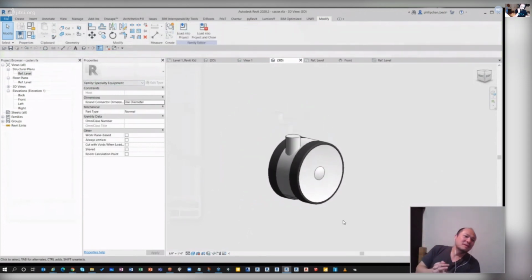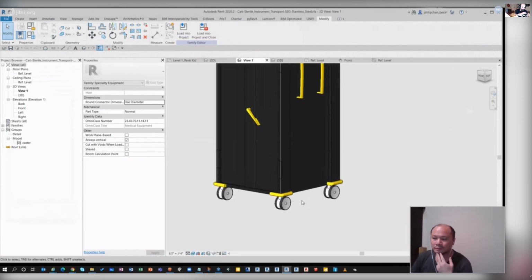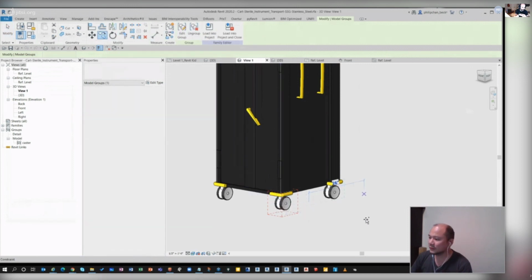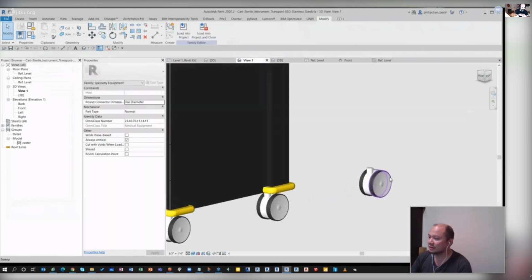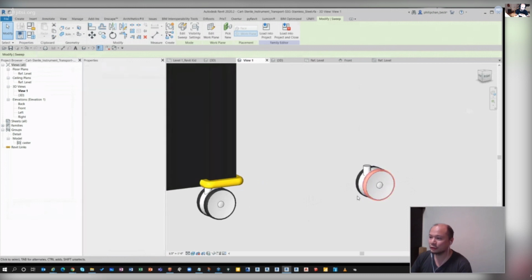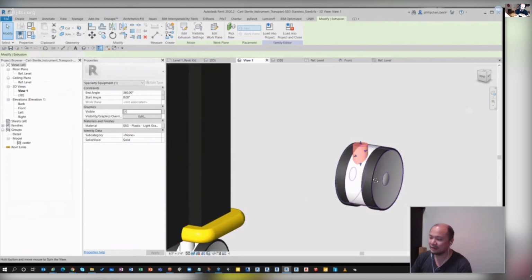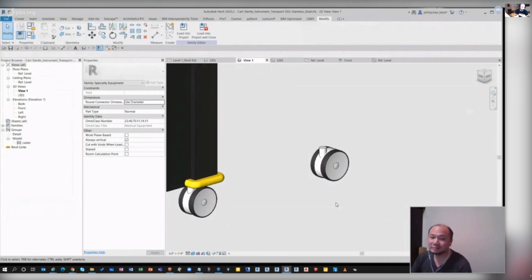I'm just going to reiterate it so everyone follows. The geometry was built in the other family. Then you just make a group out of it, and then you can save the group out. So this wasn't a nested family. This was obviously built. So any of the other casters that were in a group were just individually modeled elements. Yep. So I could move this out here, and if I ungrouped it, these are just a bunch of sweeps and revolves, all the things that were natively built in this host family. It wasn't a nested family to begin with. Very cool.